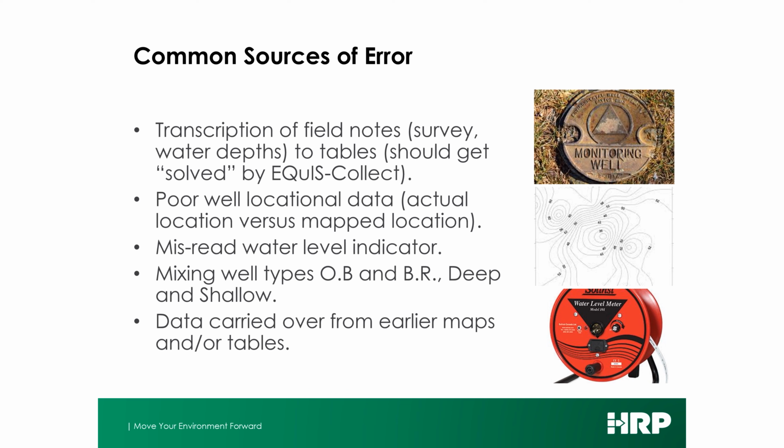Some of the other things problematic are mixing well types. I've seen people, there's shallow and deep overburden wells, and they're trying to contour them both into the same data set. Sometimes it's all you've got to work with. It'll give you something. It's better than nothing. But if you can avoid it, don't do it. Similarly, don't mix overburden and bedrock wells. Things happen very differently in those media. And again, sometimes that's all you've got to go with. Sometimes the overburden water goes away and all you've got is a rock well, and that's your first water. It's justifiable to use at that point.